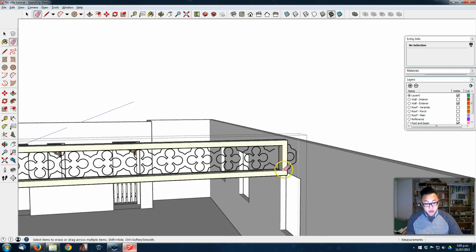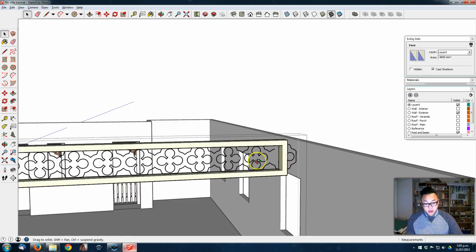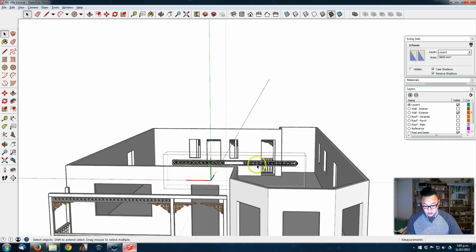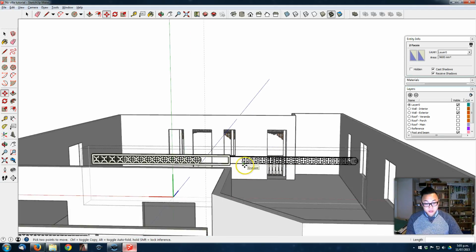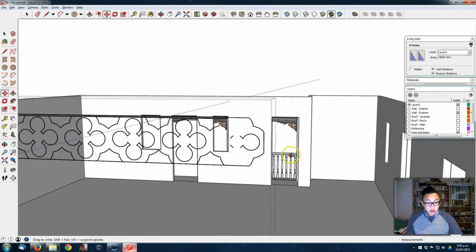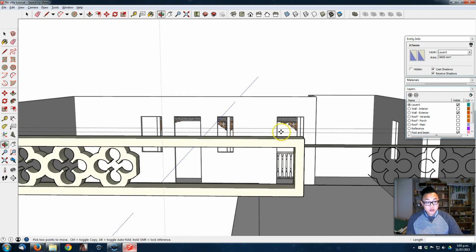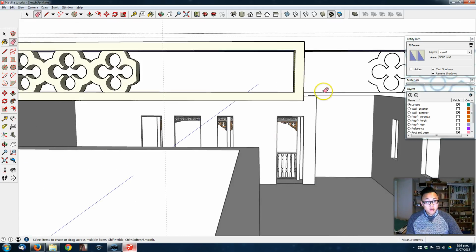And let's try to pull back those faces here. Select one, shift, so you get the two faces selected, and try to pull them back. Cool. So you see, because some of the line was still attached to those faces, now we can just delete what we don't want.